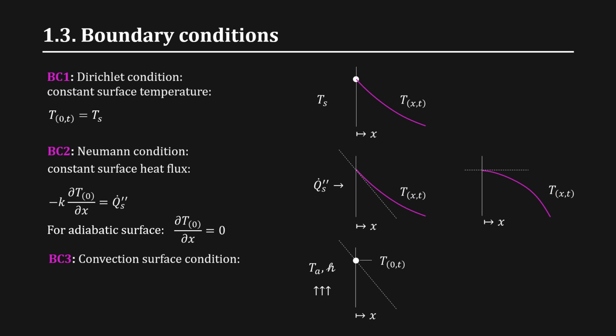This means heat is transferred through the movement of the fluid, and we can write the energy balance equation between conduction and convection from the other side. In other words, Fourier's law of conduction equals Newton's law of convection. So these are the boundary conditions which help us solve the conduction equation.